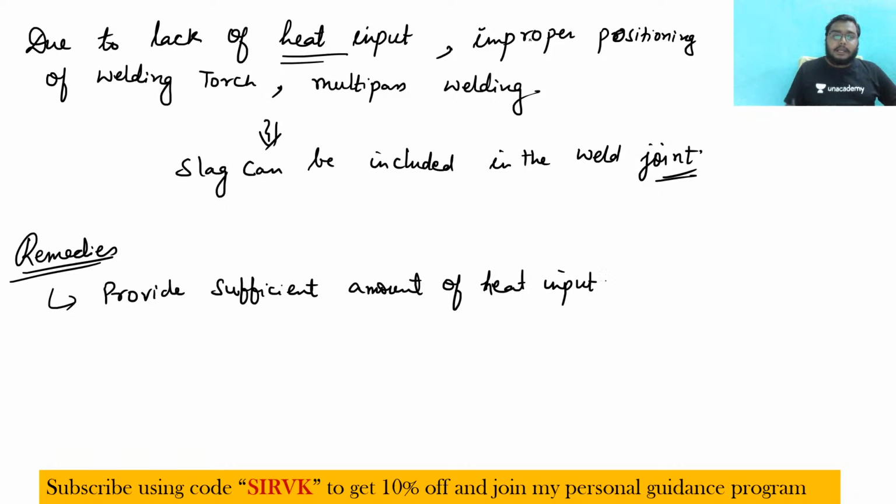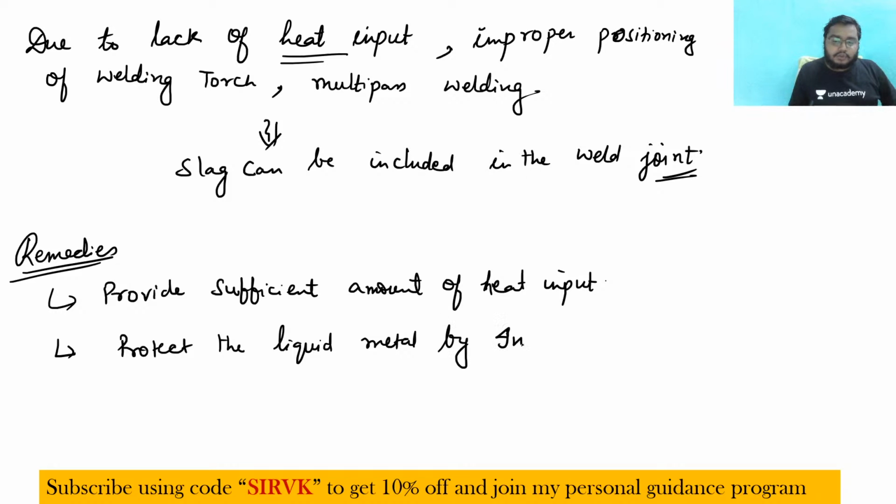And what is happening: improper positioning of the welding torch, some outside material is getting in, slag inclusions are happening, and an oxide layer is also forming. So let's do one thing: we protect the liquid metal by using inert gas. Using inert gas means shielding gases.